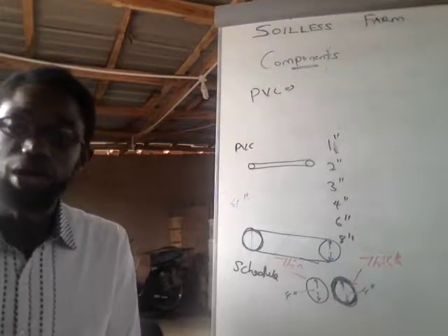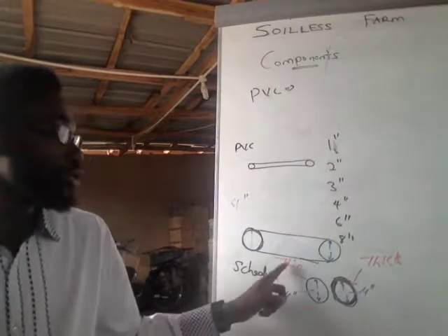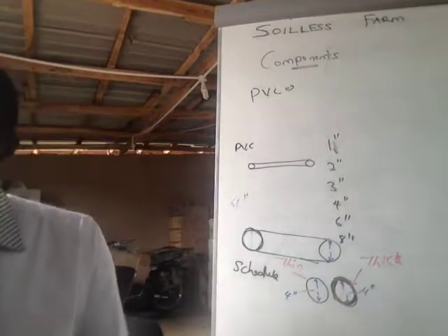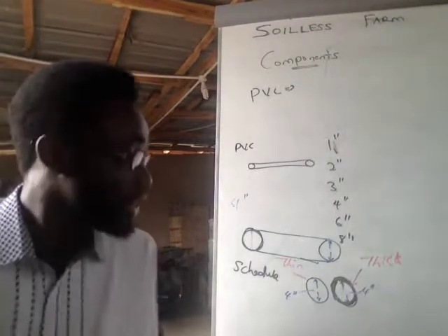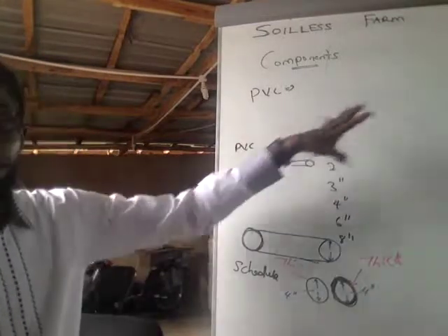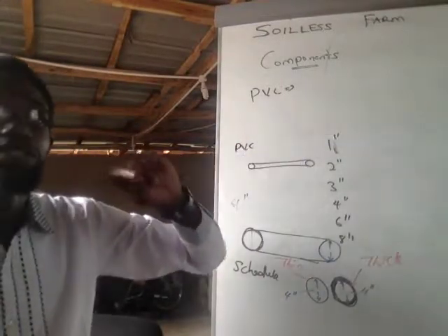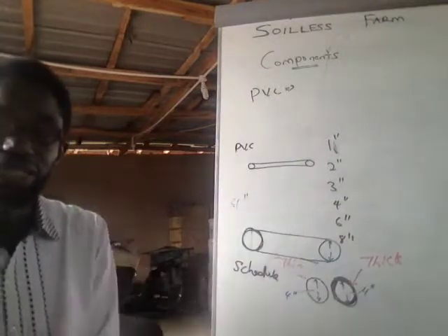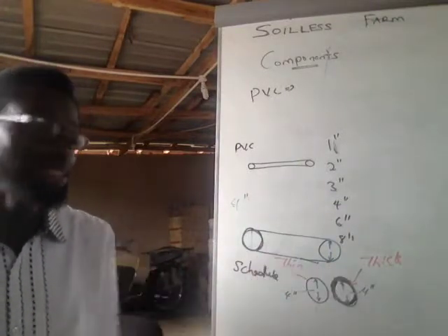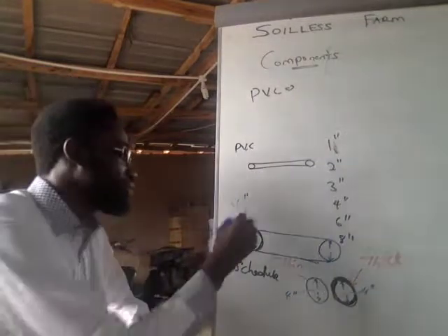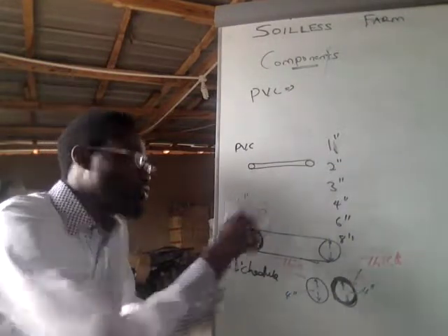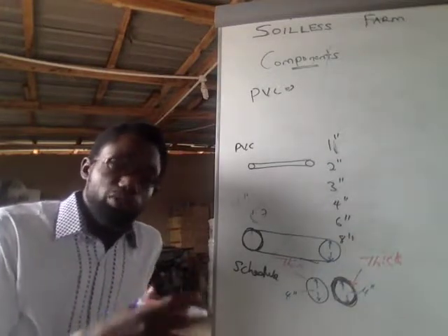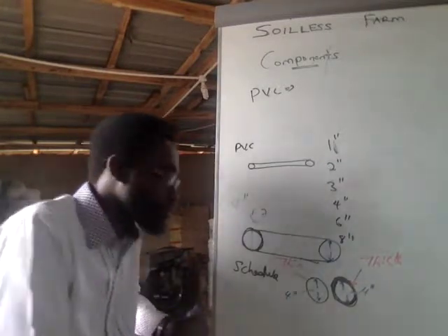For the purpose of aquaponics, hydroponics, you can actually use your thin schedule. It works perfectly. So please take note of that. So this is on naming the long PVCs. Then depending on where you are buying, they come in different specific lengths. They're usually about 1.7 or so meters long, but they sell them in feet. So depending on where you are buying, they will tell you what the feet are.